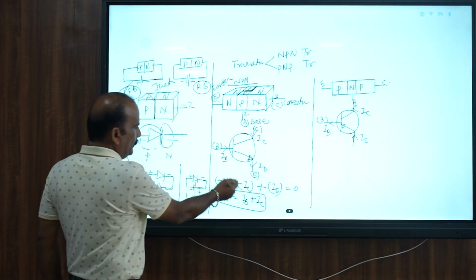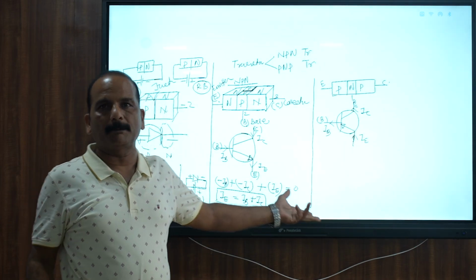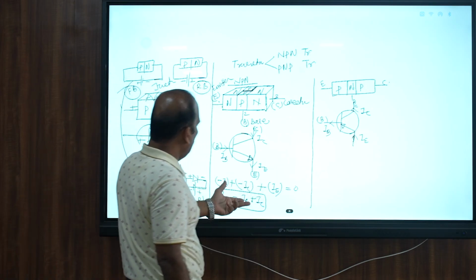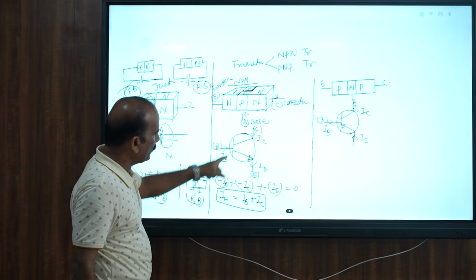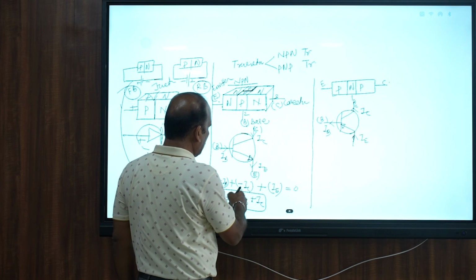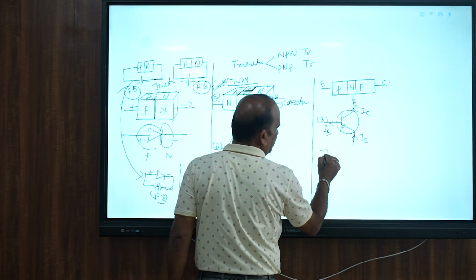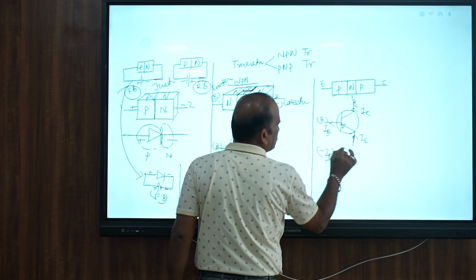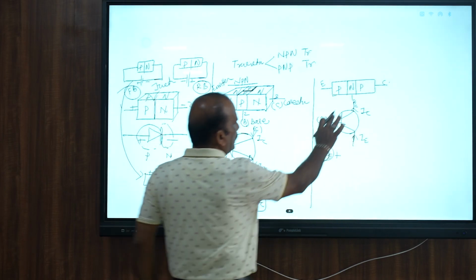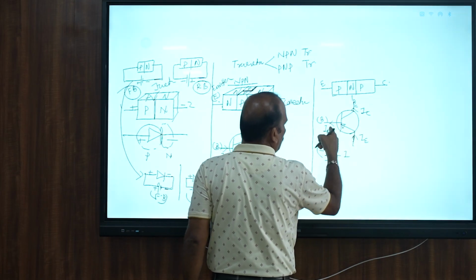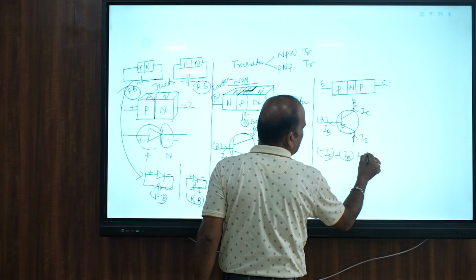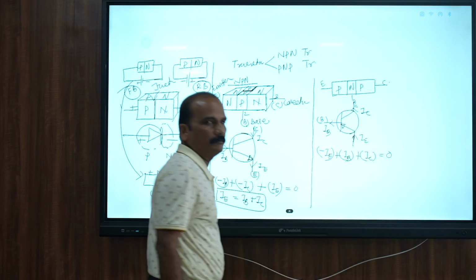Accordingly, putting the same algebraic sum of the currents meeting at a point in a closed loop as per Kirchhoff's current law, here we are taking incoming current as negative and outgoing current as positive. We will take the same fashion there. Incoming current as negative, that means minus IE, plus all outgoing currents, which are positive: outgoing current IB and outgoing current IC, equal to 0.